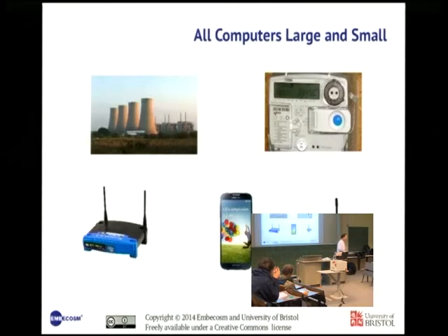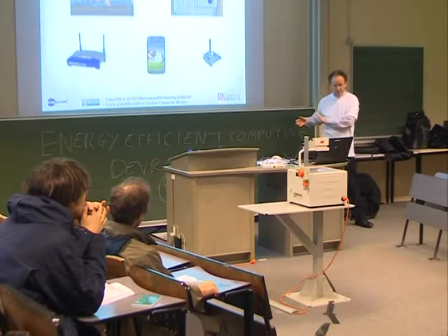And lastly is energy scavenging. Now, energy scavenging draws on tiny amounts of electricity. So this one's a little hobbyist thing, a little Zigbee transmitter that can pick up stray electromagnetic radiation and get enough energy to run the Zigbee protocol. But other applications are devices that are implanted in the body, so you don't have to plant a battery with them, sensor devices that can pick up scavenging. And those devices use incredibly low amounts of power. Nanoamp currents, nanowatts of power.